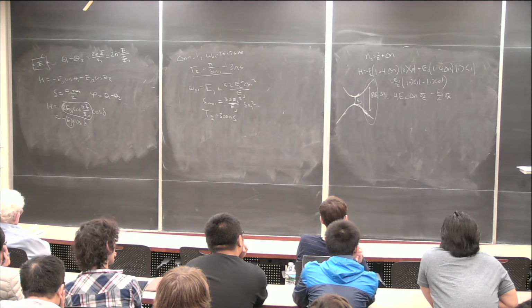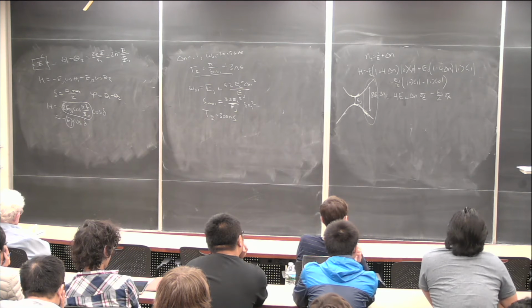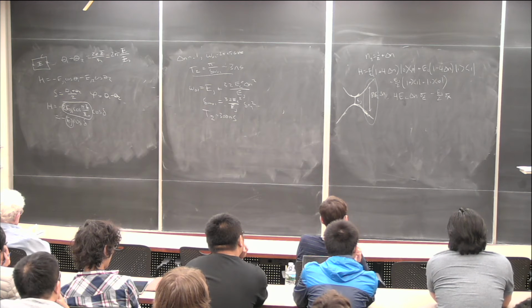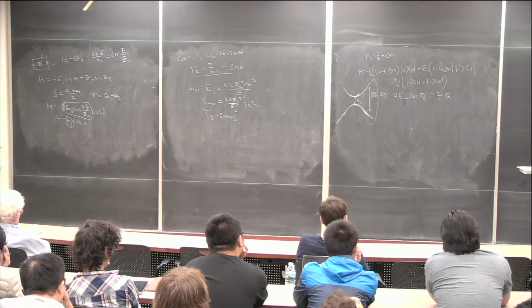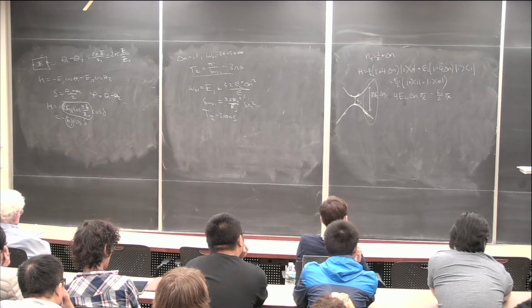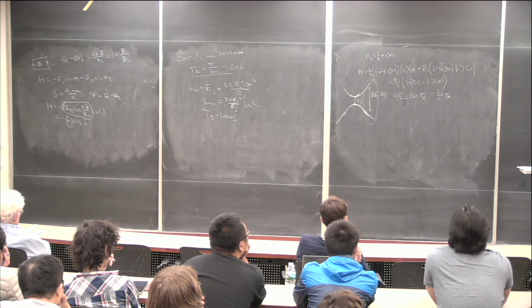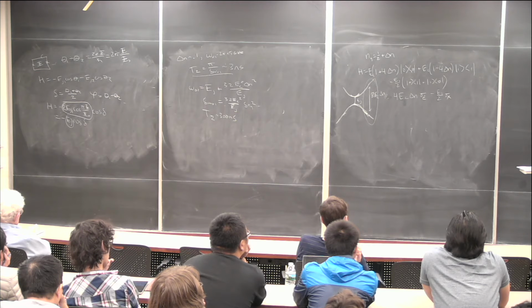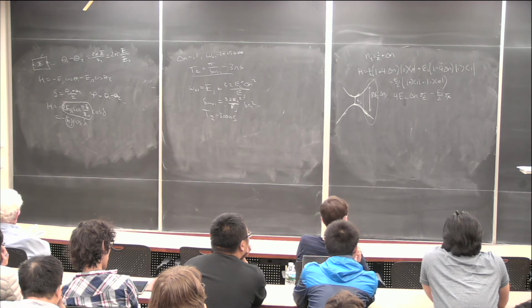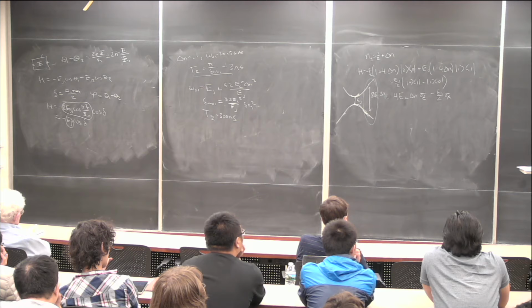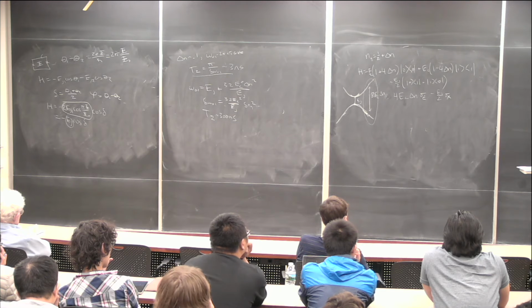Because what you would do from an experimentalist perspective is you would bias your device up to that charge point, and then you would do your experiment, and T2 would be 300 nanoseconds, and you'd be really happy, getting great data, smiling and laughing. But the noise was not zero mean, and so you would slowly drift off of that charge degeneracy point, and 20 minutes later, you'd be hanging out on the side where T2 was 3 nanoseconds, and everything would fall apart.